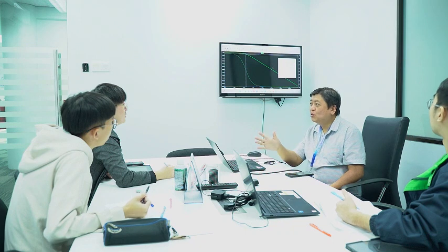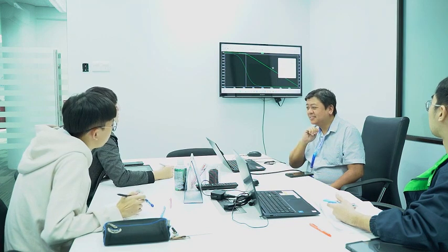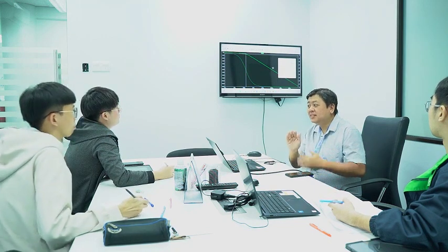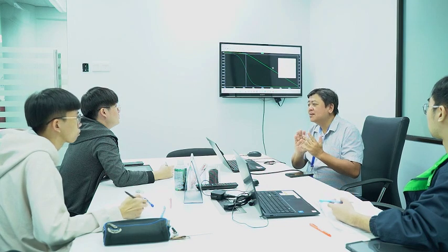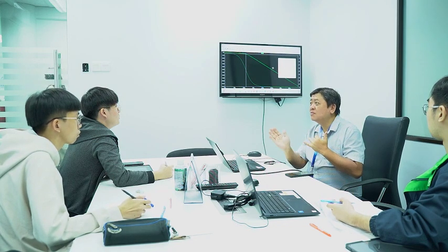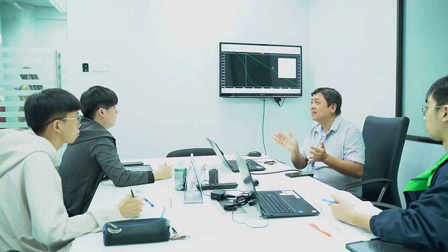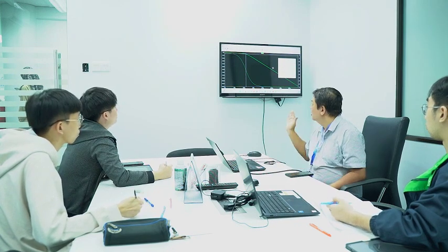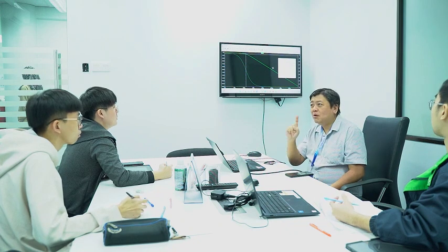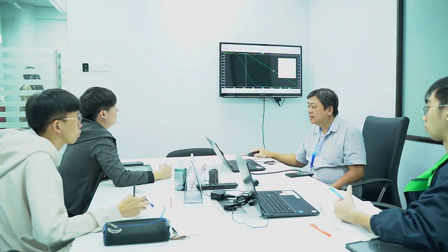When you have one pole and reach your cutoff frequency, the phase shift is 45 degrees. 45 degrees is already a lot of delay. That's why we never use any input frequency more than your cutoff frequency. Half of the delay is already done. For one pole, what is the maximum delay? 90 degrees. You see or not?